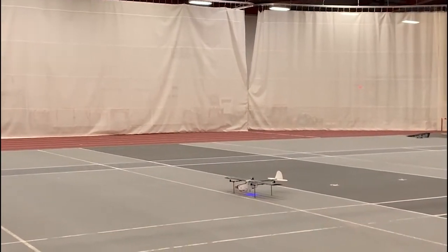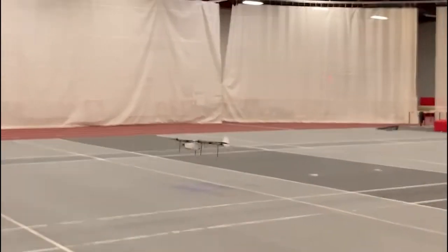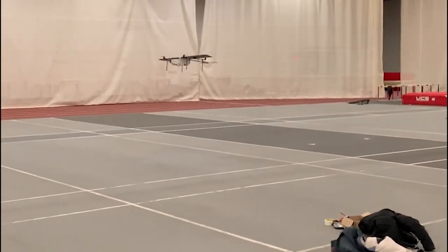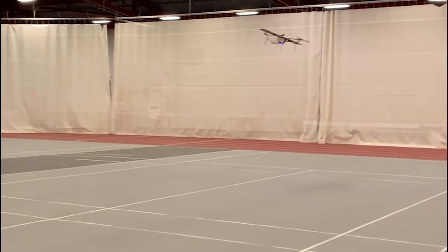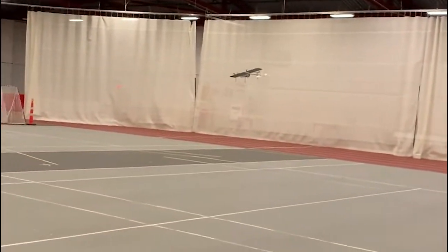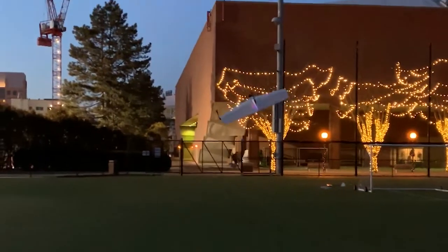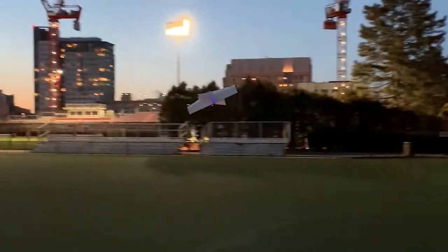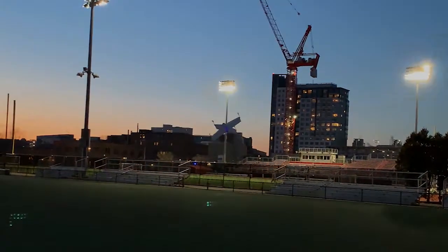For example, in order to enter gliding mode after hovering, the quadplane controller simply redistributes thrust between front and other rotors without needing to change its orientation too much, while the X-wing has to lean forward by a lot to transition from copter mode to gliding mode.